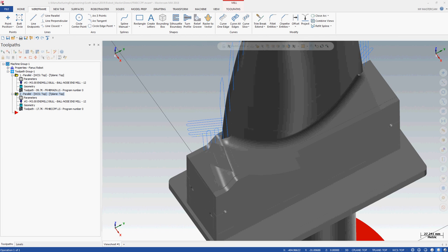So all I do is create my surface. I go back into the model assembly because my work coordinates is now coming from here. I don't want it from wherever this was created. And file, export the parasolid, select it, and then I throw it into here, which I've already done. But so now I go back into Mastercam.